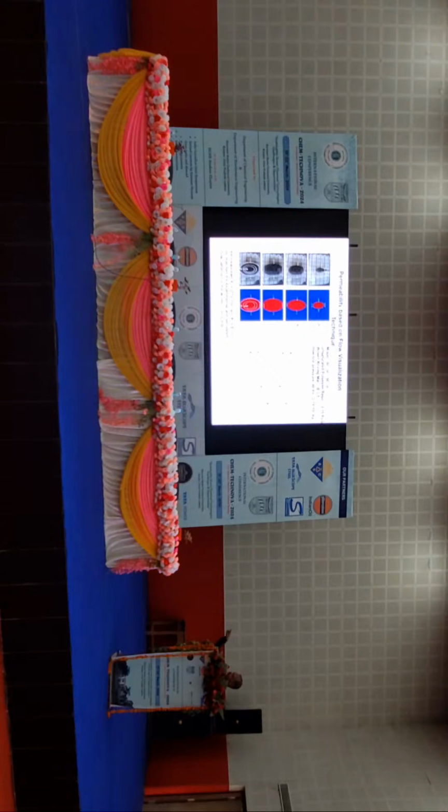So for this experimental setup, a mold of 80 centimeter by 50 centimeter, unsaturated polyester resin, woven roving mat of porosity 0.5, and injection pressure of 40 psi, I get Kx as 2 into 10 power minus 10 meter square and Ky as 5 into 10 power minus 10 meter square, which exactly match between the experimental and simulated flow fronts.